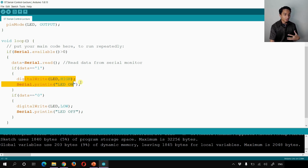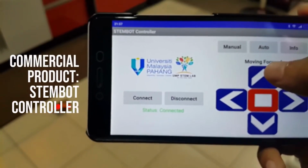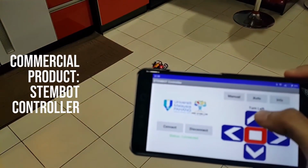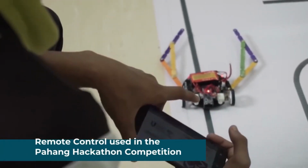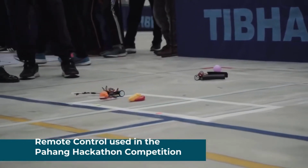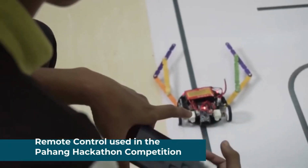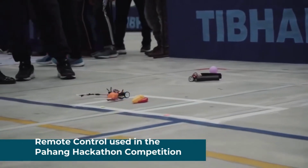And if you want to explore a more advanced version, I have also designed and developed an Android app to control the STEM board. That remote control only transmits single characters: F for forward, R for reverse, L for left, and R for right. As simple as that, just single characters, and then the Arduino IDE program translates that information to control the motor direction, so that it can turn left, turn right, go forward and reverse.